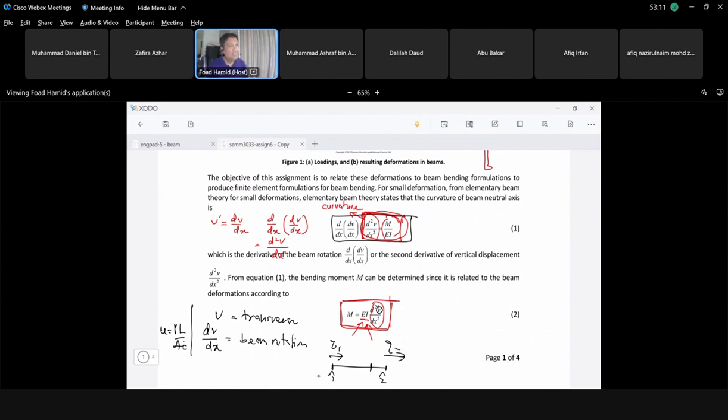So how do we do this? We use the shape function, N1 Q1 plus N2 Q2. This is for the bar element, and of course N1 is 1 minus Z over 2, and N2 is 1 plus Z over 2. I don't think I need to go back into that discussion, because by now I think you should have mastered this.